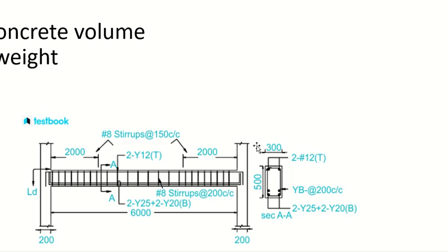Then what else? Should I add or subtract anything? What should I subtract? I did it for the stirrup as well. Look at the stirrup. What did I subtract? The cover. Okay, so I need to subtract the cover. Cover same, right? And for each side. So 2.